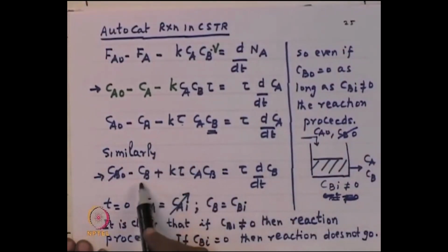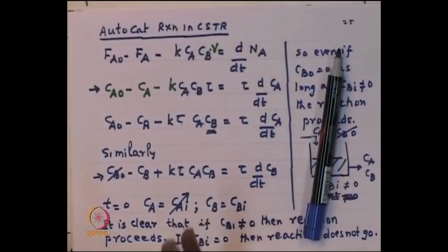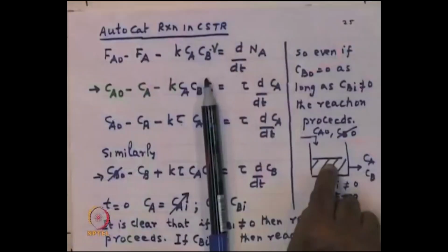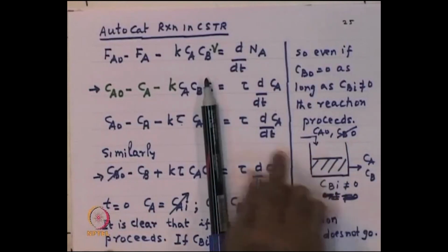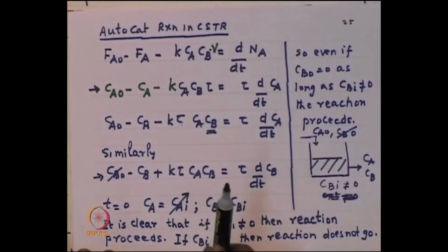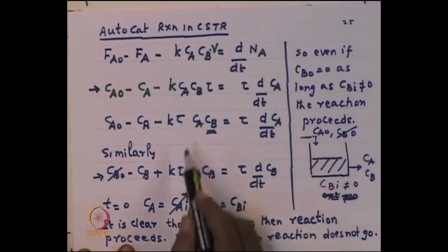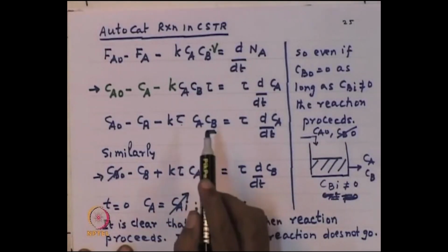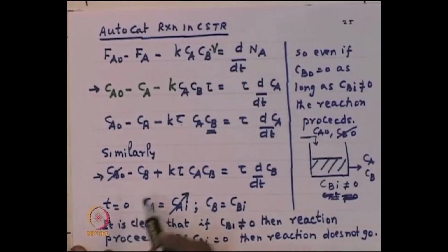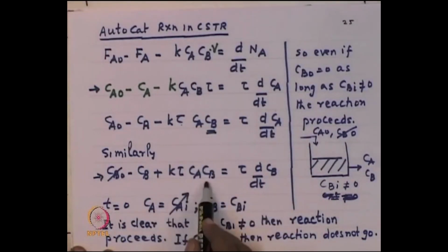See here, what we are saying is that the continuous input of Cb is 0. See what happens, please, it is a very important question, let me answer this question. Whenever we have an equipment, we would start up that equipment sometime in the past. After all, we have to start the process someday in the past. At the day when you first started that process, if you had put Cbi into your tank, Cbi would be active, however small it may be, so that Ca times Cb becomes finite after time 0 plus. Therefore, this reaction takes off.